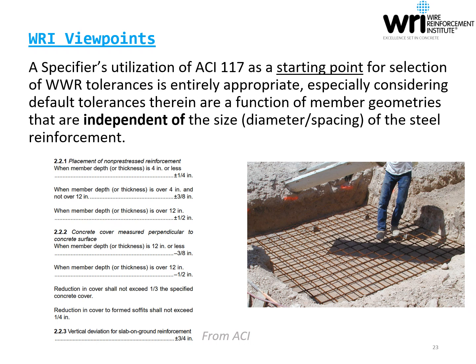After all, the composition of welded wire reinforcement material has the same modulus of elasticity as rebar given they are both steel, and the presence of welded intersections on a welded wire reinforcement mat would typically only serve to help stiffen the overall reinforcement assembly, not make it more susceptible to displacement. The takeaway here is that ACI 117 shouldn't be considered off limits to those who are seeking a jumping off point for default tolerances related to welded wire reinforcement.